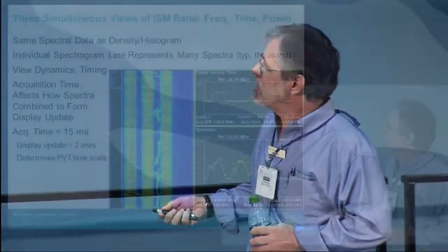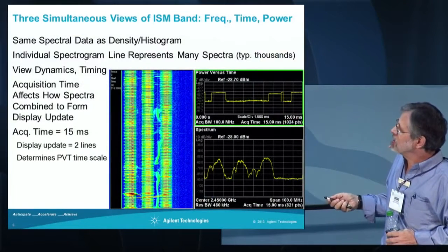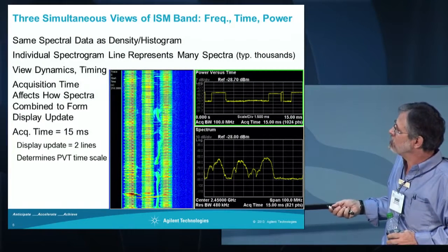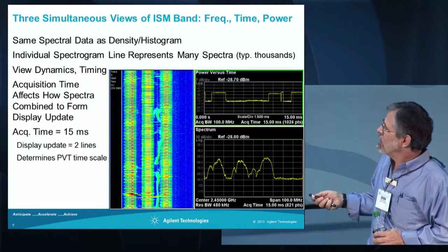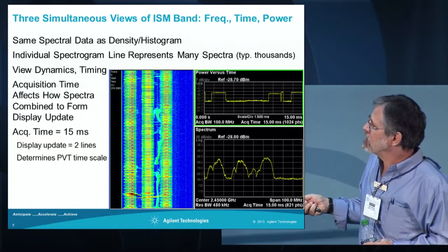And you can see in this case, the wireless LAN signals, the wide ones, seem to be sort of pulsed. You see some channel scanning going on here, and then you see some odd signals here, which may well be some of the microwave ovens we were talking about, or some other signal wandering through. You really don't have any guarantees in this band.